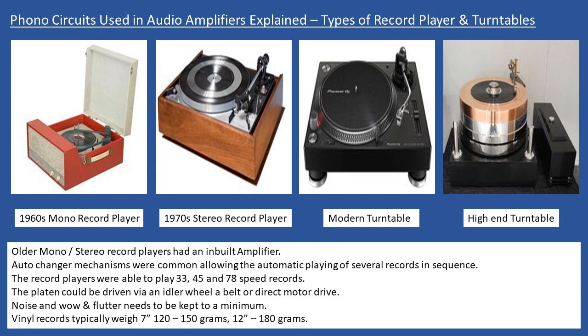More commonly now, a lot of turntables are direct drive, so there isn't a belt or an idler wheel. They are mounted directly onto a motor, and the motor is providing the rotation. But in terms of the motors, this is another important point. Some of the very, very high-end turntables don't use metal bearings. They use ceramic type bearings, because with any motor you will have noise generated. I'm not really referring here to electrical noise, though yes, it can happen. It's more around mechanical noise, and we'll mention a little later why that is important and what amplifier manufacturers have done to minimize the effects it creates.